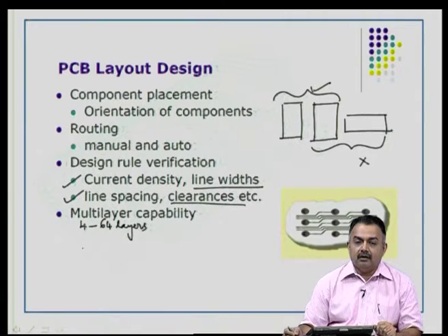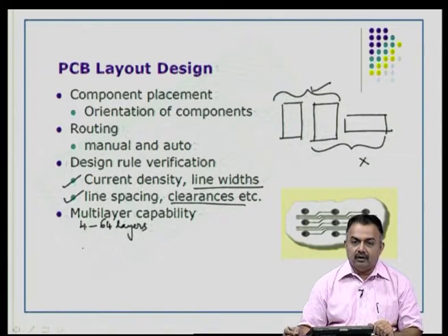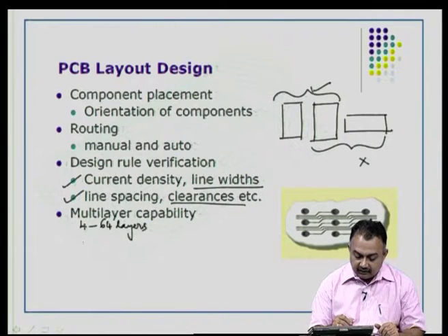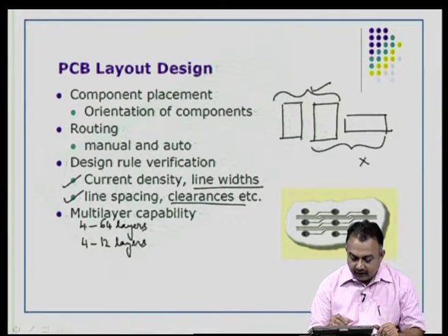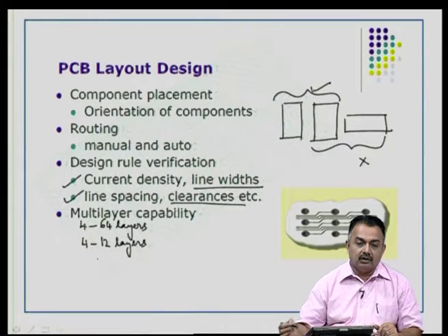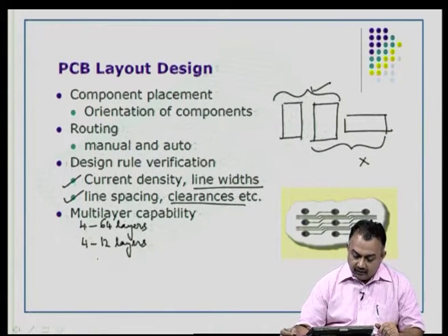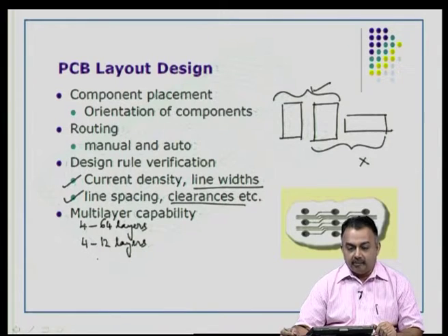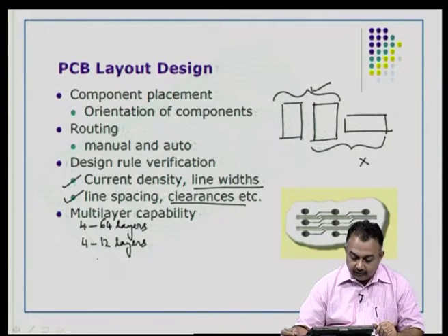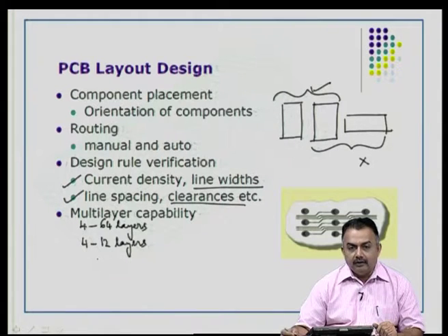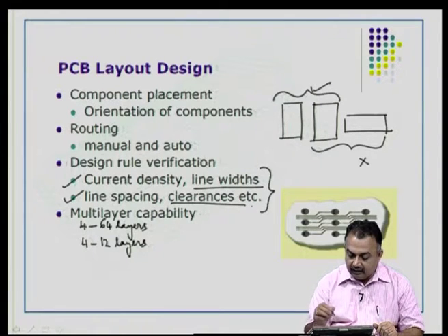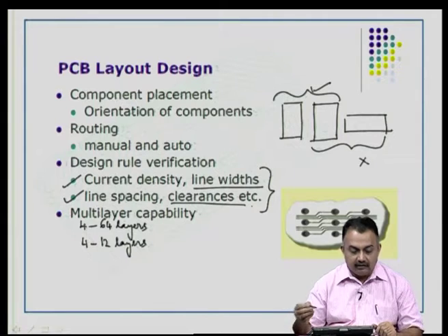But obviously, in a commercial board or in a handheld device or a communication product or a desktop motherboard, you will not require this many layers. Typically, the handling capacity will be around 4 to 12 layers. Higher layer count is usually for more strategic applications. So, multi-layer capability should be possible using your layout. We will also talk about various other parameters that I mentioned here, like the clearances that are required at a later point of time.